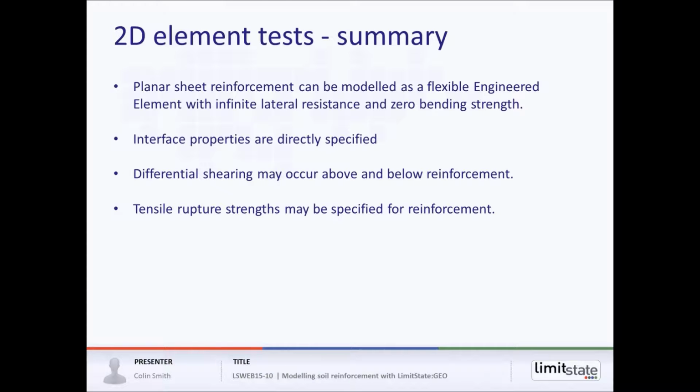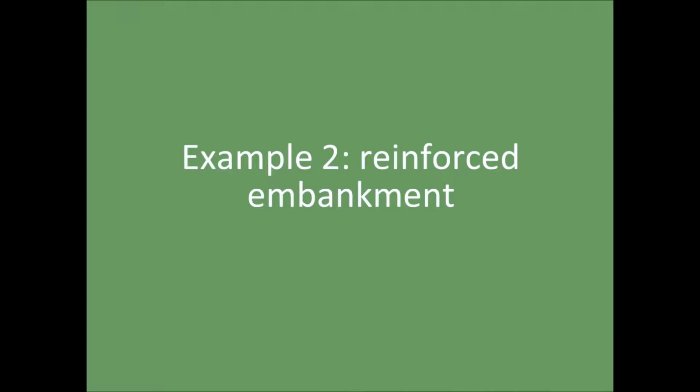For 2D models, we can directly specify interface properties and allow for differential shearing above and below the reinforcement, and also model tensile rupture strength. So what I'll do is look at some element tests just to illustrate how the reinforcement is modeled, and we'll do that with the following model. So let me just pull that one up.